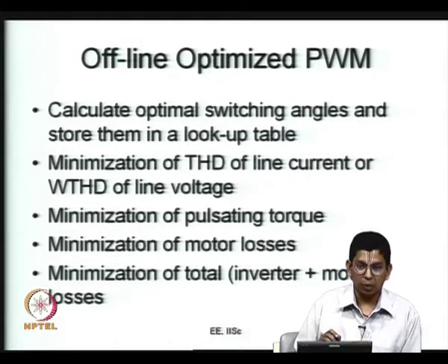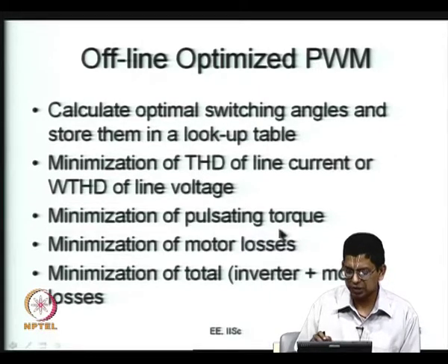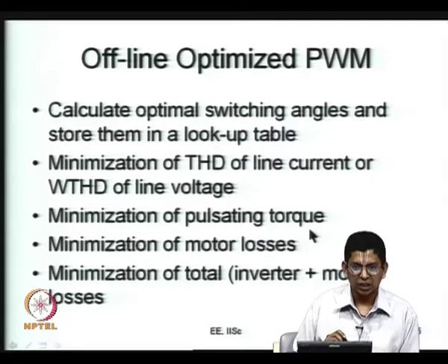In the same way, the fundamental current and the harmonic fluxes interact to produce the pulsating torque. Also, the harmonic fluxes and the harmonic currents can interact, but that is negligible because harmonic fluxes themselves will be negligible and harmonic currents will be negligible, and their product would be much more negligible, so you do not have to worry about it. So, what causes pulsating torque is, one, the fundamental flux interacting with harmonic current, and the other, the fundamental current interacting with harmonic flux. An analysis can show you that the fundamental flux interacting with harmonic currents is what is really higher. So, it is really the cause of harmonic current.